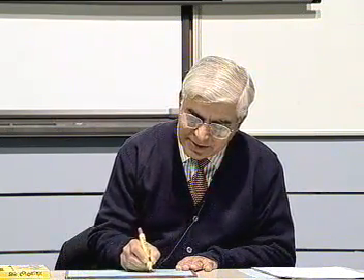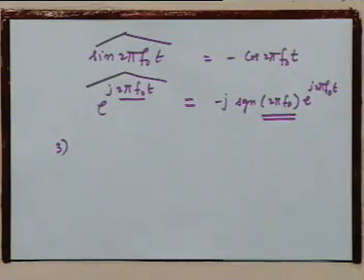All right. What can you say about the energies of x(t) and x hat(t)? What is the relationship between the energy? Suppose x(t) is an energy signal. It will be the same. Why? Because mod of H(f) is equal to 1, right?